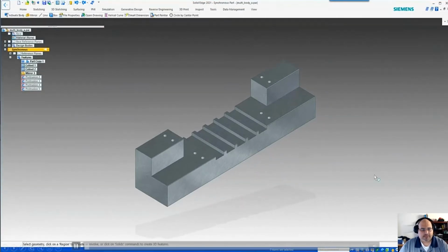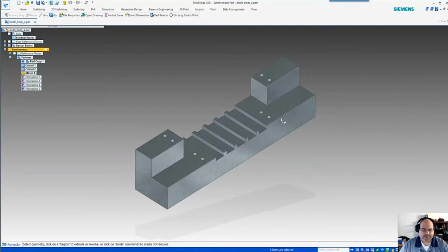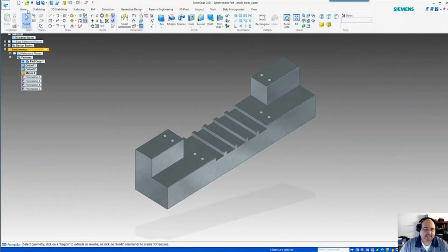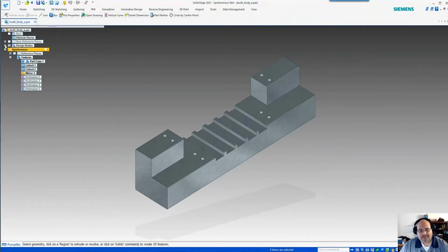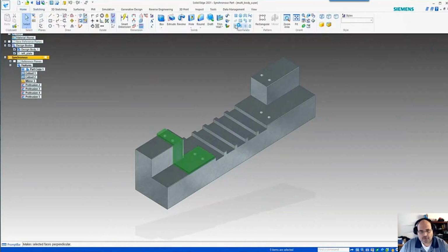And with the extra piece part components that it needs, I got some part plates that need to get attached to this, as well as the sheet metal part. So you can see that right now it's just a regular part file, and I already created one of the plates over here on the left hand side. So from the actual part environment, I'm going to come over to add a body.